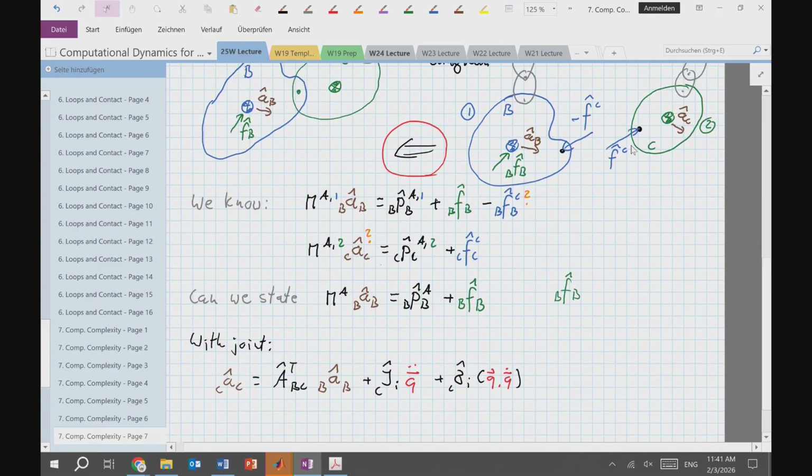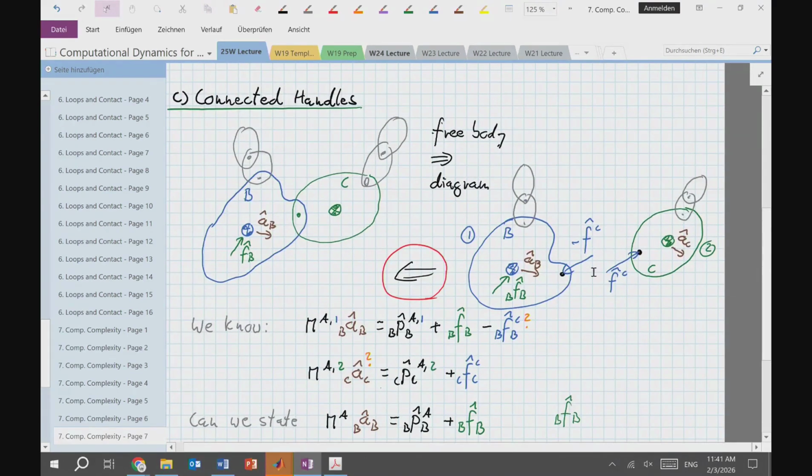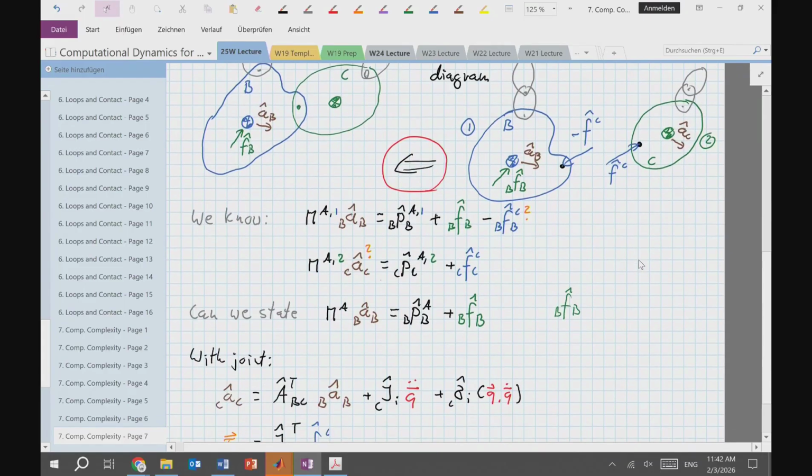If I now think about the constraint force here, we have a very similar equation, or we've seen similar equations in the past, where I want to project my constraint forces into my joint space, which is going to use the same Jacobian that I postulate exists here, now with a transpose, multiplied with my constraint forces that occur within this joint.